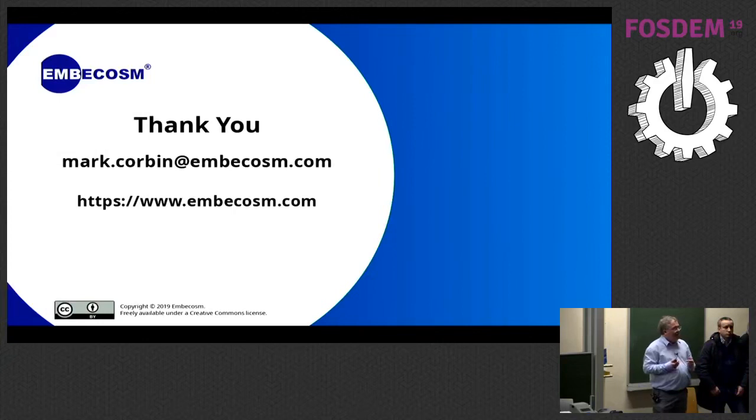It does help. I never really spent any time with Buildroot, and if it helps me turn on things fast, we want to give it a shot. Yes, of course, there's corporate backing behind Yocto in terms of board support layers, and some of the members provide that sort of backup for board support packages. But I think it really depends on the type of system you're trying to produce and maybe the number of people you have working on your project.